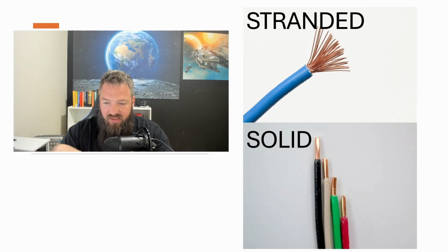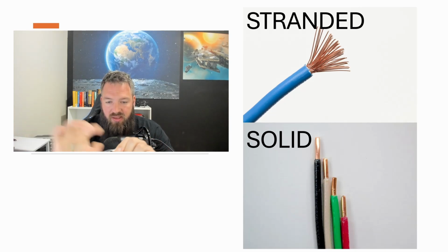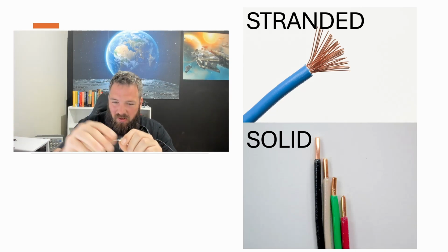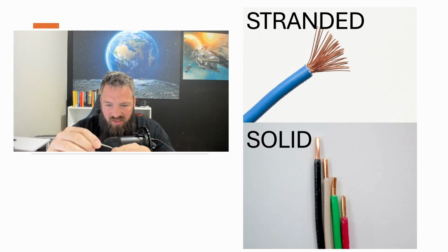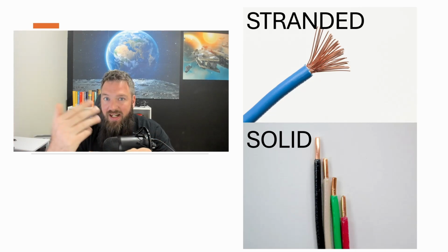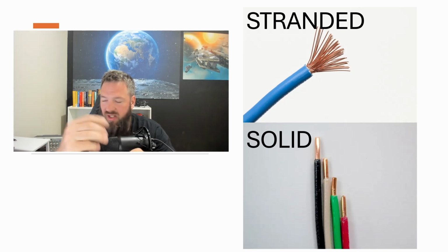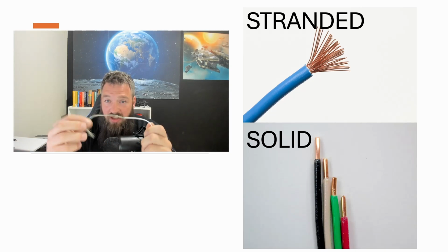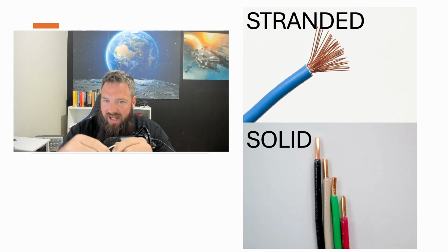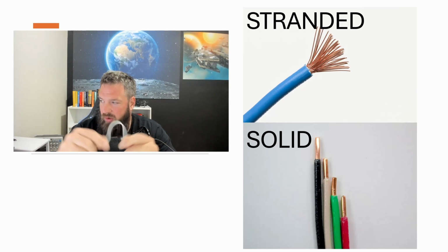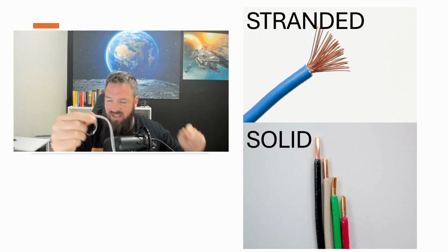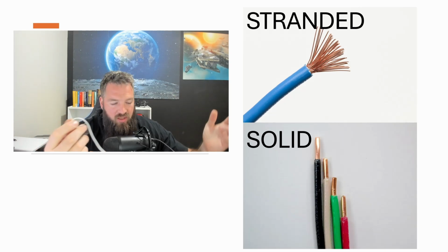The disadvantage is you have reduced current carrying capacity, so you're going to have a higher voltage drop as you go with distance. This is perfect for things like automotive, things that are moving. If you're moving a lot and you don't have to worry about that voltage drop, you're going to use this type of wire because it'll be reliable for your application. It's flexible, you have a high vibration environment, and you won't have to worry about that.